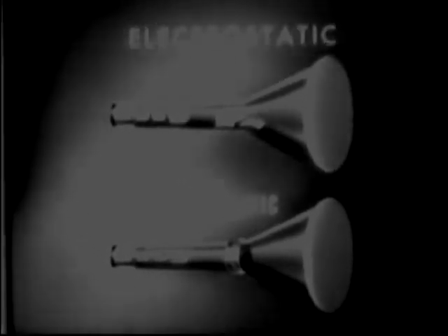At the rear end of the tube is an electron gun, composed of a heater, cathode, grid, and focusing anodes. The cathode, when heated, gives off electrons, which are formed into a stream by the grid. The anodes accelerate the electrons and focus them into a beam. The beam bombards the fluorescent coating on the face of the tube and causes it to glow with a bright spot of light. These plates deflect the beam horizontally.